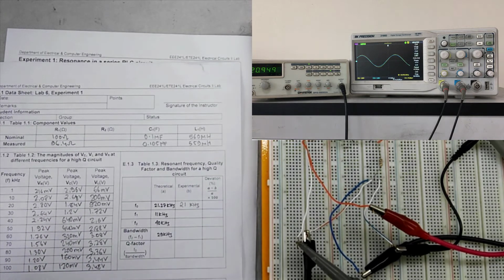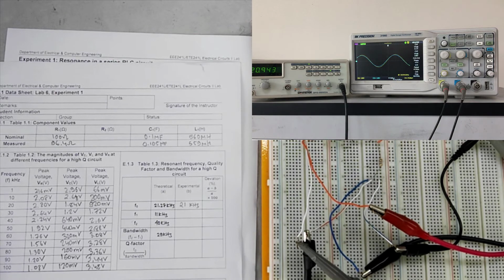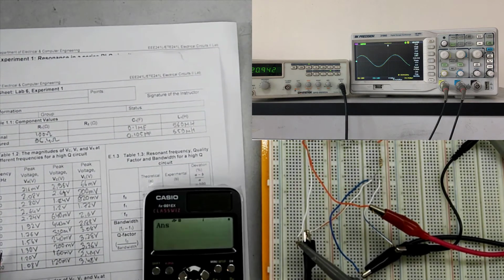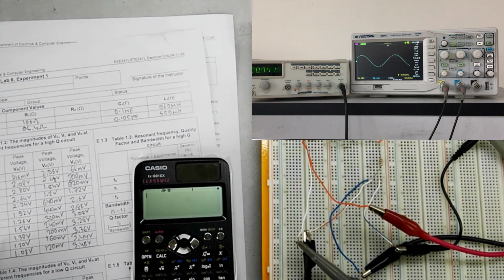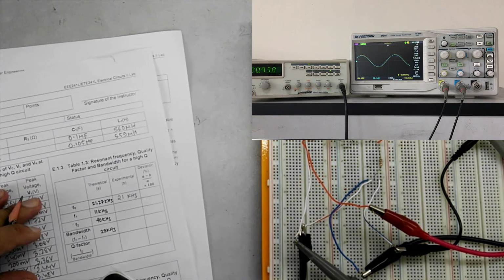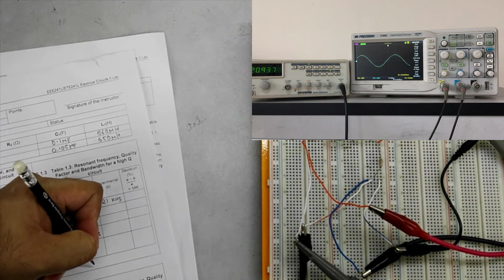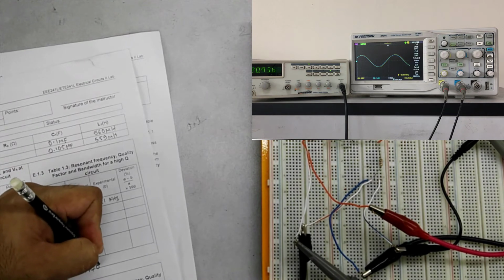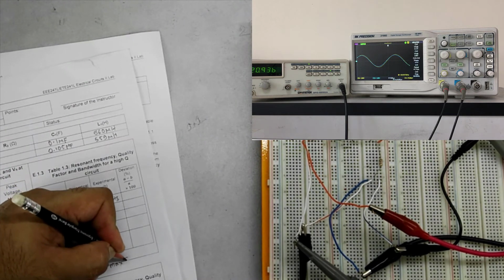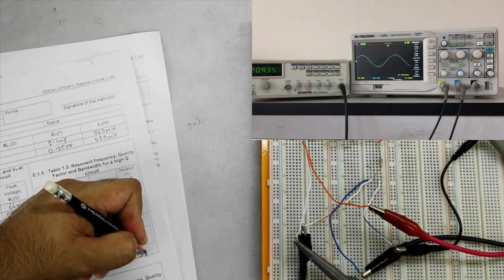So let's determine the voltage where we should look for these frequencies. So 2.80 volt into 0.707, 70.7%. So that is 1.98. So 0.707 Vmax is 1.98 volts.